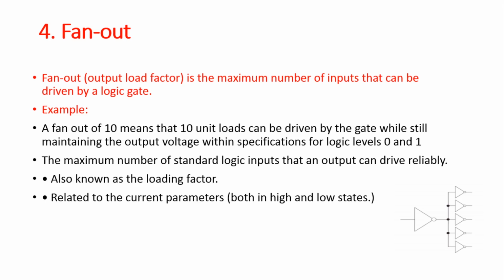Whereas the next one is fan out. Fan out is the output load factor, the maximum number of inputs that can be driven by a logic gate. For example, a fan out of 10 means that 10 unit loads can be driven by the gate while still maintaining the output voltage within specifications for logic level 0 and 1.